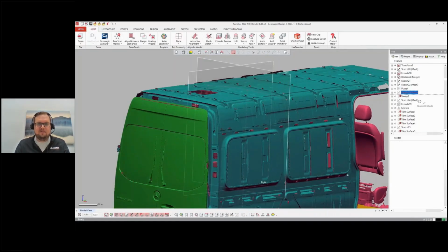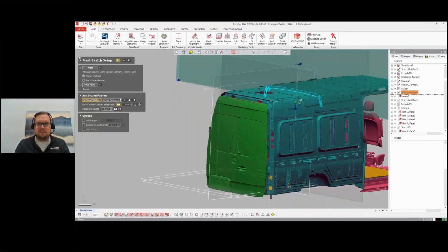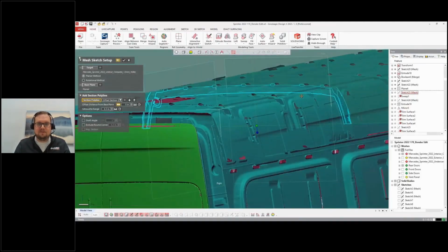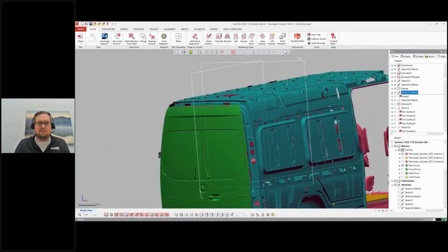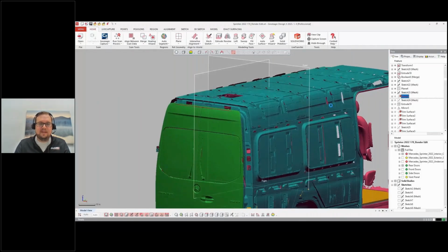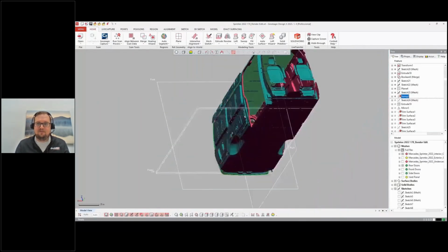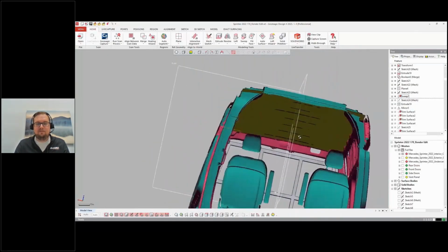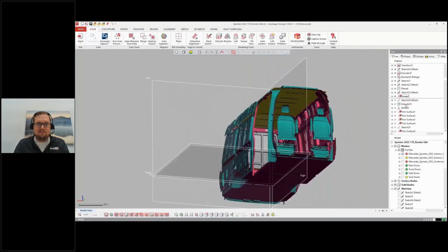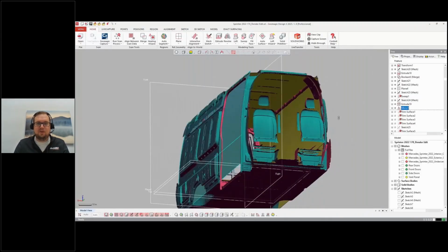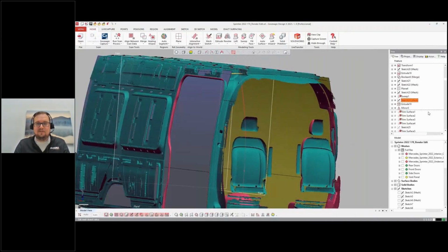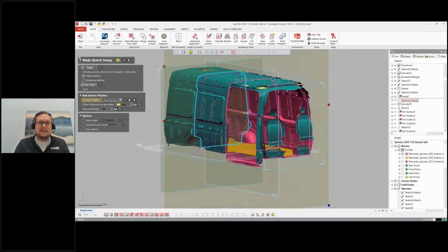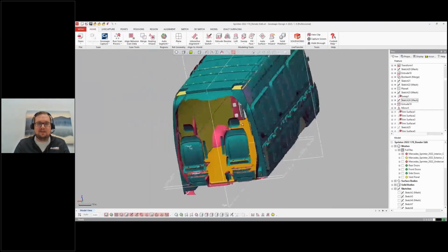Now we need to create a bit of a shell here. So we need to panel our walls. So I'm going to grab, again, a silhouette here of our upper ribs, our vehicle ribs, and it's going to allow me to get the curvature. Now, if you've ever cut a flat piece of plywood and tried to fit it to a curve, you know that it shrinks on the sides. So this will allow us to make sure that when I put my curved piece in, I have the exact length of that arc that needs to be cut. And again, whether we bring that into something like a CNC router or water jet or any of the above, we're confident that we have the material that we need.